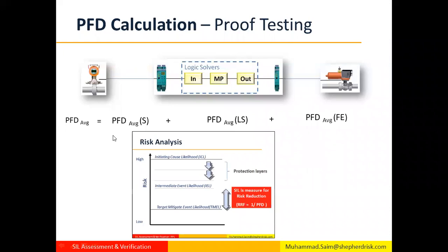And then we compare this with the target risk reduction factor we set in the risk analysis or LOPA. And we compare if we are meeting the PFD for the function with the risk analysis requirement.